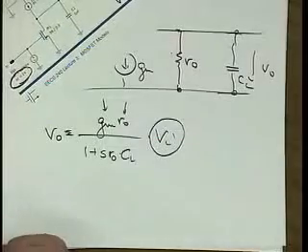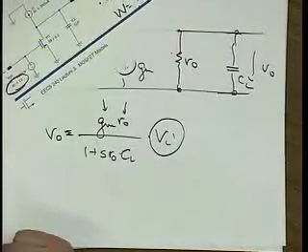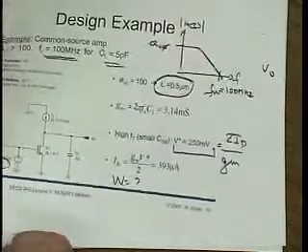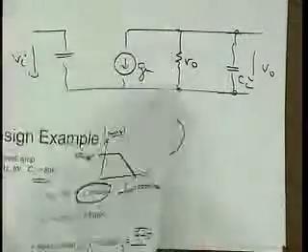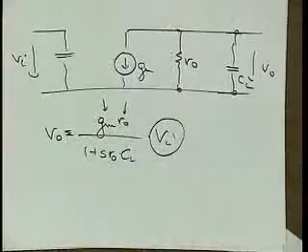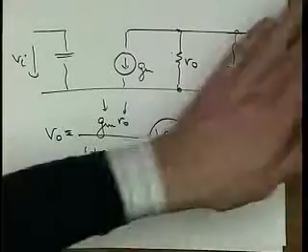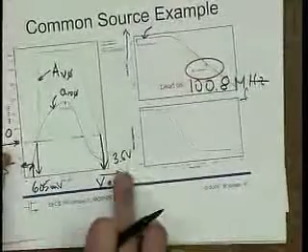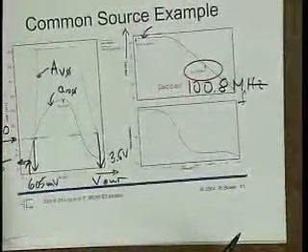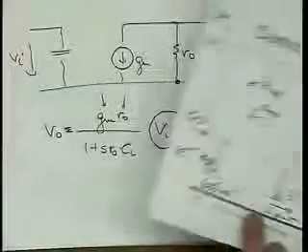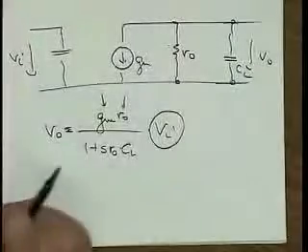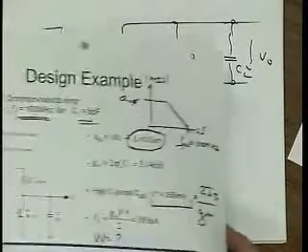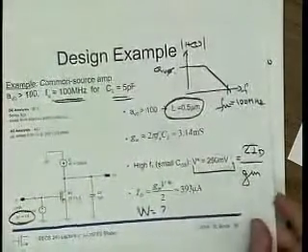How did you pick that range for VGS to sweep from 800 millivolts to 900, just arbitrarily? Your experience? Well, that I guess is in the next slide, right? In the circuit schematic on page 39, you mentioned in the DC analysis you sweep VGS from 800 millivolts to 900 millivolts to get a bias point.